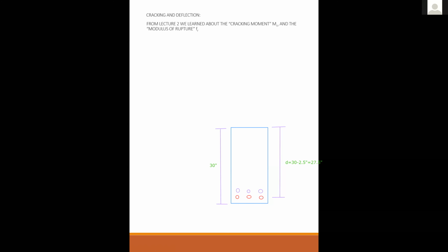Okay. Now Professor, do you take into consideration the 2 rows when you're finding the D min? Because he had 25.59, I think you said. Do you take the 2 rows into consideration there or after? Well, after, because he didn't realize that the area of steel precluded him from putting it in 1 row. So when he minuses the 2.5, he should have minused 3.5 instead of 2.5.